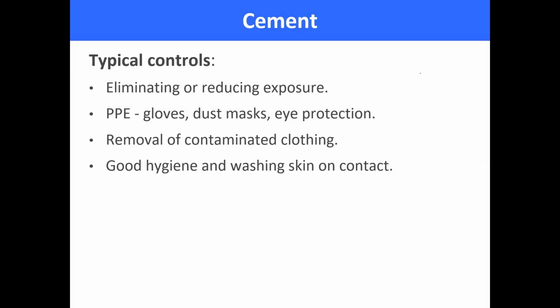Cement control measures: you need to eliminate or reduce the exposure. Don't let cement sit on your skin. Provide PPE, gloves, dust masks, etc. Remove contaminated clothing and make sure you follow good hygiene.